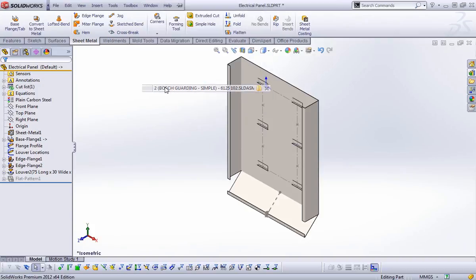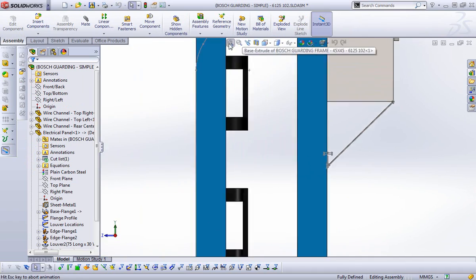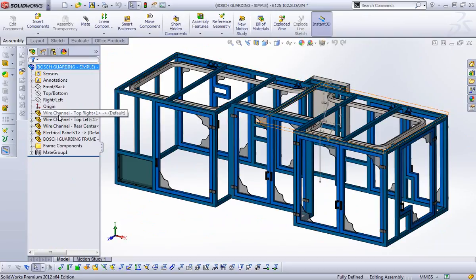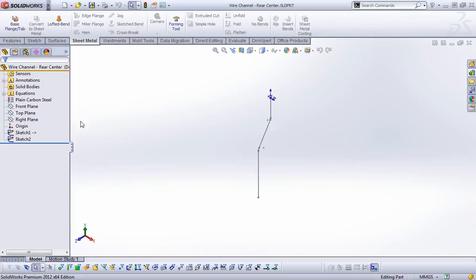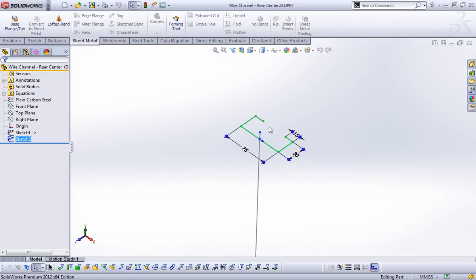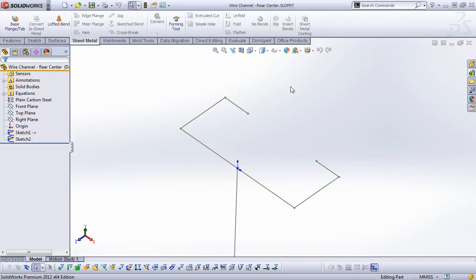So if I come back over to my example file, I've got a path on this part already. You can see this part right here. I'll also go ahead and open it up by itself. What I've got is a sketch that is related back to that assembly file, 300 millimeters. You can see it's just a typical sketch path that you would have for a sweep. And then the profile is the channel that I'm going to sweep along. Notice that it is an open profile, so I don't have to have the closed profile of the extruded shape. This is making the assumption that everything is formed.